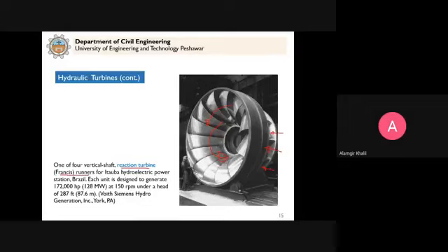And finally, it will be connected on the other side, at the center. It will be connected with the shaft, and it will rotate the shaft. So this is how the water flows, and then the turbine converts that hydraulic energy into mechanical energy in the form of a rotating shaft. So this is the runner of the reaction turbine, the Francis turbine. Clear?